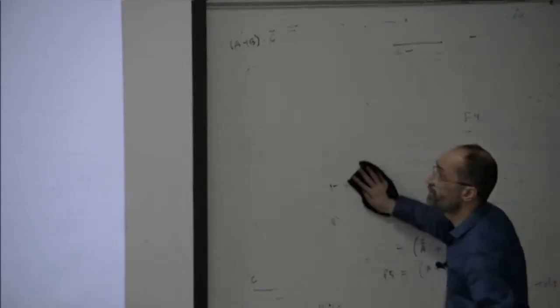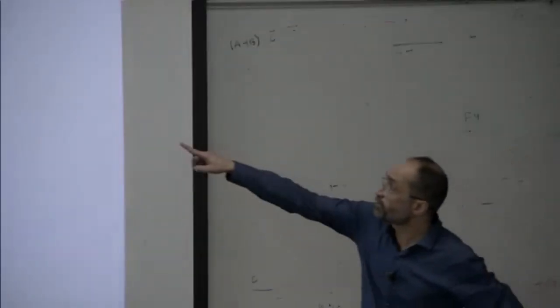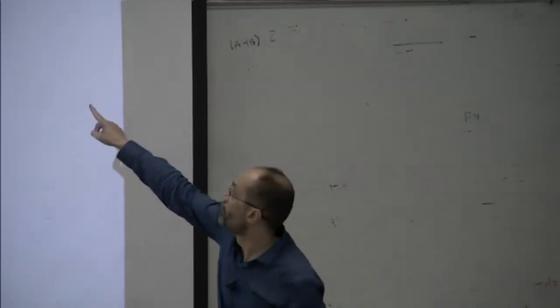Can you see here which function we are implementing now? XY. What is Z? XY whole bar, and then X bar plus Y bar. This is the De Morgan's theorem that we apply. Now, we can also implement an inverter here.